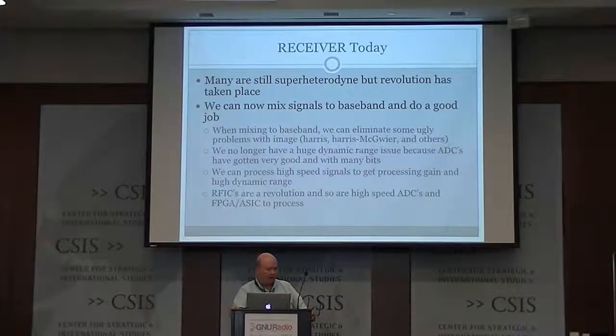And I can easily put something in front of these ADC converters that makes them sensitive enough to hear weak signals and linear and resistant enough to take strong signals at the same time, and allow me to do the selectivity, the decoding, detection, etc., all in software. So nothing's changed except everything's gotten smaller and the ability to do things has gotten faster.